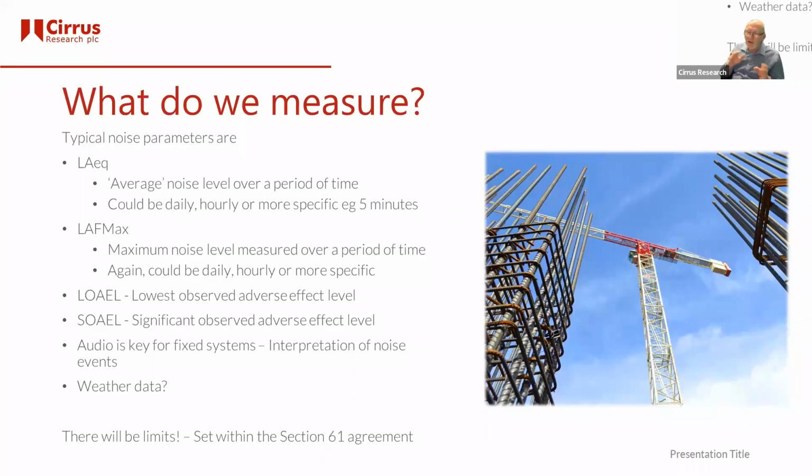And your noise management plan, or what's in your section 61, will specify the sort of data that needs to be logged. Now with modern systems, you can specify for the actual noise monitoring system to instantly give you a 1 hour or a daily or even a 5-minute average result. But obviously you can post-process that if you need it over different time periods. So there's ways of getting at that data. But we're looking at average noise levels.